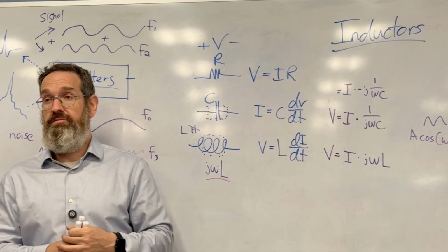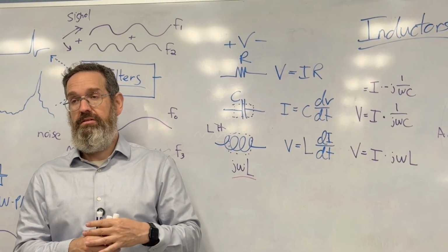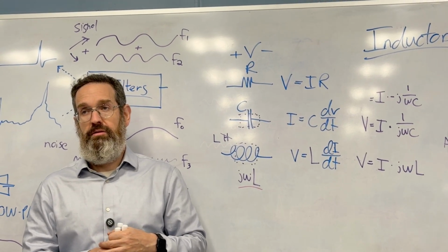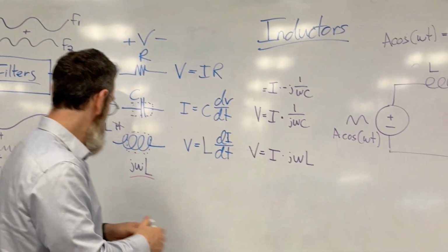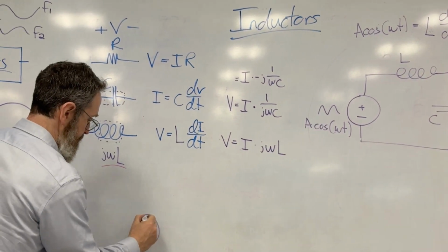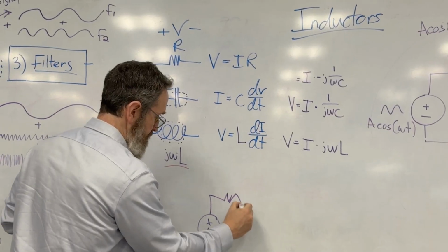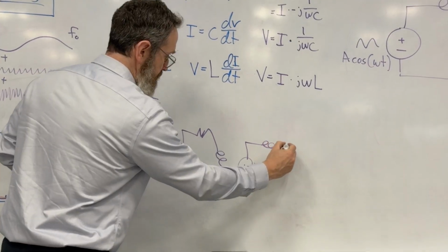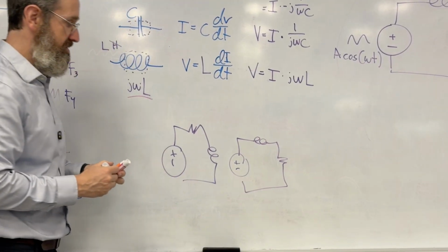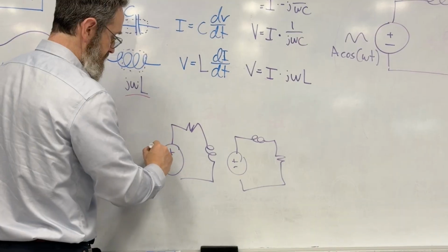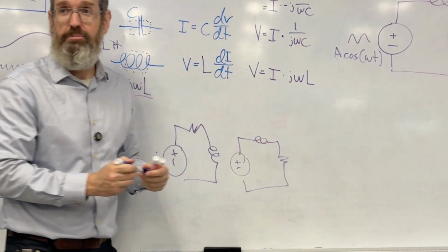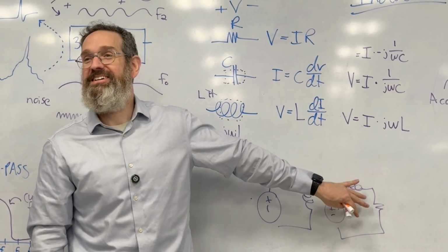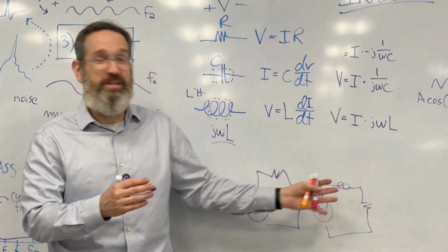Yes? Previously, when we had the capacitors with the resistor, the transfer equation changed when the relationship changed. So for the high pass or low pass. Same thing here. The first example we did was the resistor, then the inductor. So when it's the inductor, then the resistor, you have these two variations. Or think of this as the input and that's the output. One of these is the high pass, one of these is the low pass. But guess what? It's the opposite position compared to the capacitors. And if you worked it out, you would see it.